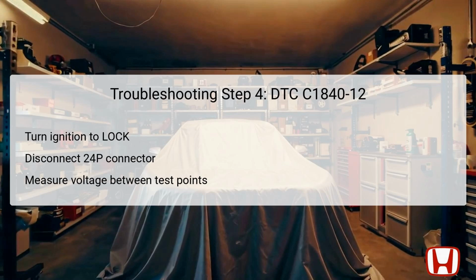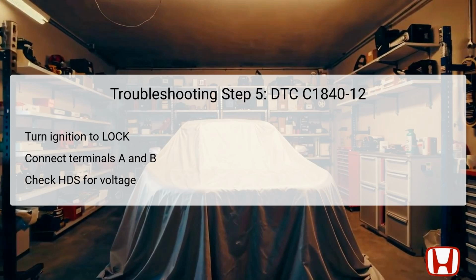Specifically, test point number 2, which links to the body ground, should reflect a voltage reading of 0.5 V or higher. If the reading matches or exceeds this voltage, it confirms that the wire is shorted to power, necessitating repairs to the PS1 wire, extending between the sensor and the real-time AWD control unit. In the event that the voltage is not at an acceptable level, you should proceed with further diagnostics to check for other potential issues.